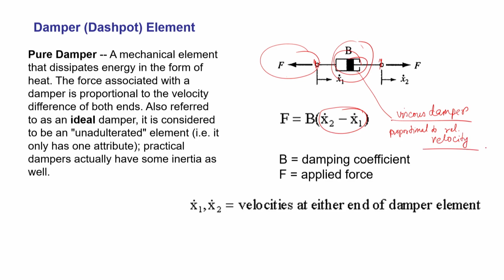There can be nonlinear dampers where it is slightly different. I can try to give you an idea of it. It is a piston cylinder system that we are trying to draw, but this piston cylinder system is slightly different, in that there are small orifices in the damper.